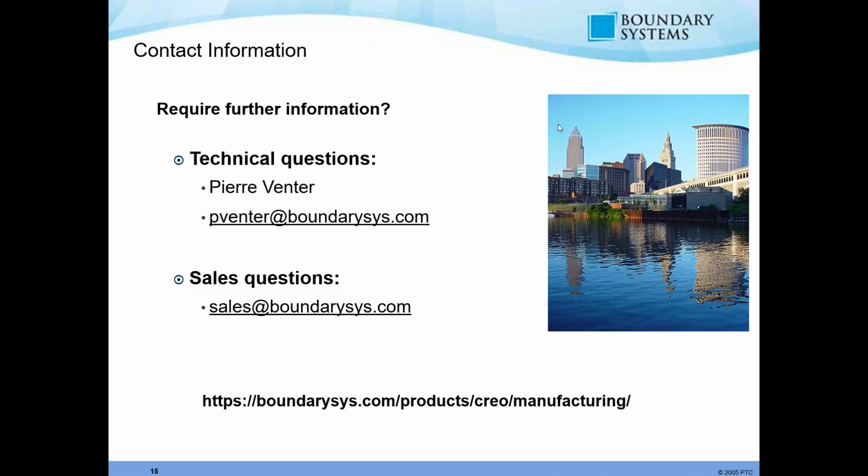So one question: if you use MathCAD in your part, will Modelcheck work okay? Can it check anything in MathCAD? It depends on what MathCAD is doing within Creo. You can't check anything in MathCAD alone, but if you link up MathCAD with Creo and it creates parameters and things like that, then yes, you can check it, as long as it is a parameter. But it can only check values within Creo, so it's not going to check your input from MathCAD. Okay.